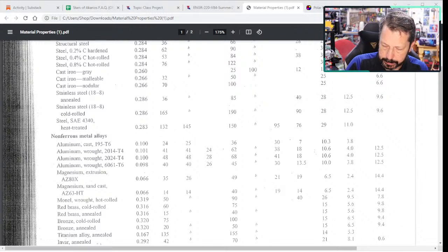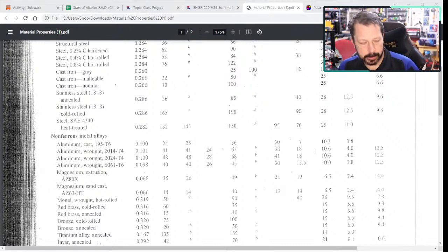Oh, this is hardly anything. 1.57 square inches. So 240 divided by 1.57 is 152.9 psi. So a super small amount of stress. We knew it would be less than the other section because there was smaller torque and larger area. So we're nowhere near failing our wrought aluminum shafts with these torques applied to them.